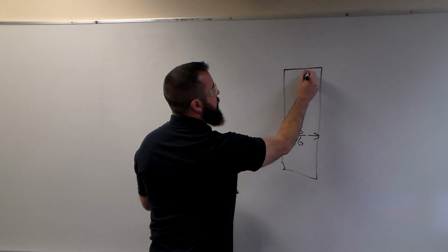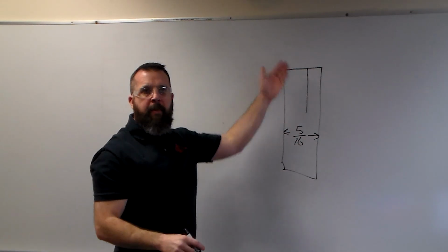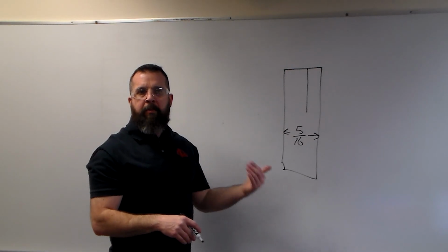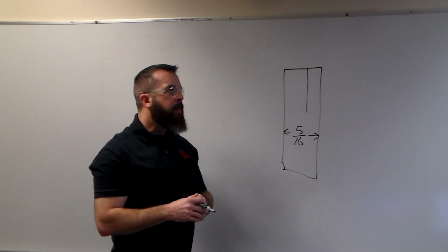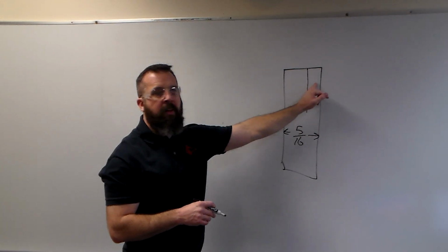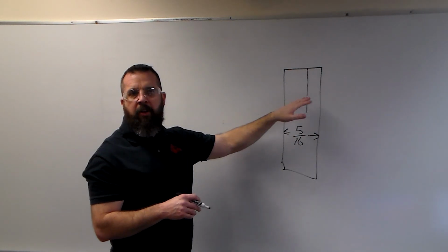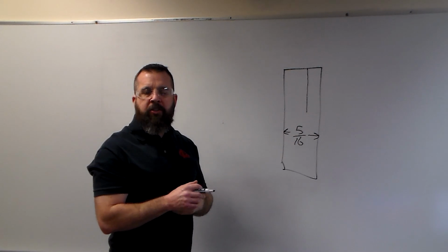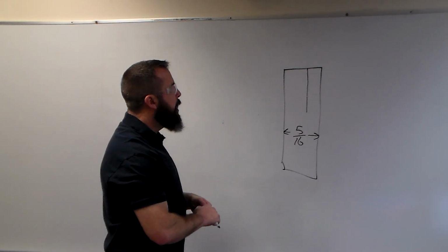It'll look something like this. And just scribe it back like 1 inch or so. You're not going to grind the tool back that far, but you'd be better off to have a really long line than a short line, because as you start to remove the material on this side, that would be the 1/8 inch side, it's going to discolor and burn away some of the layout dye. So more is better when you're scribing your line.